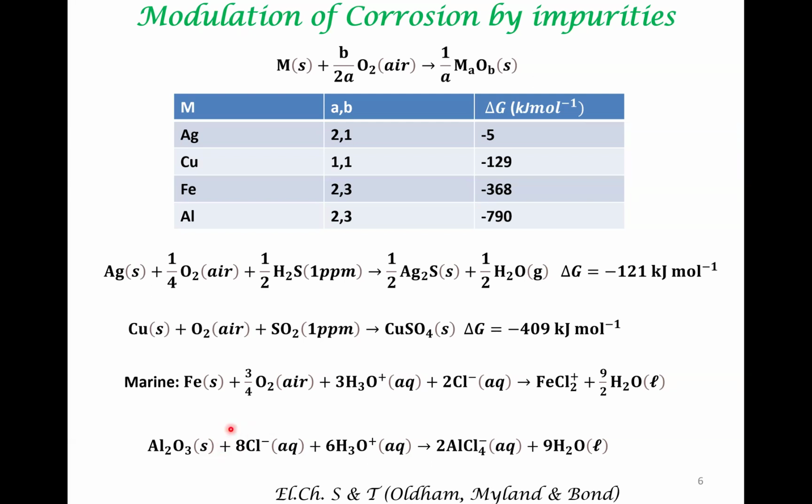Why is this important? Because sometimes NaCl, typical rock salt, mixed with certain solvents, is used as a de-icing agent. Okay, in Western countries where there is a lot of snow, you spread some salt to melt the snow, and this chloride ion can react with alumina and dissolve that passive metal oxide layer. So we will look at all these cases as we progress.